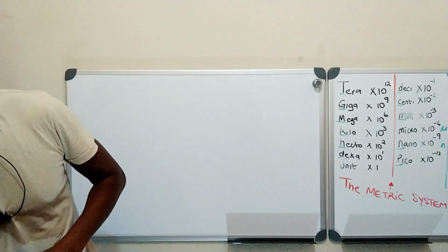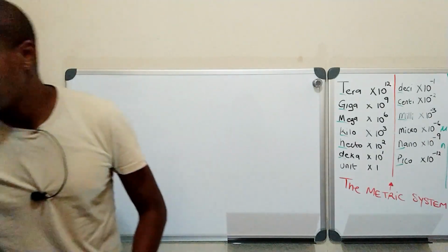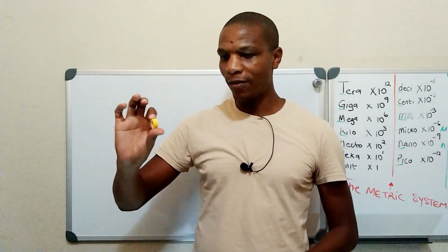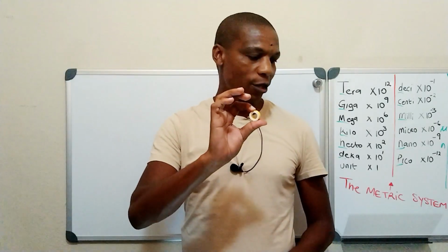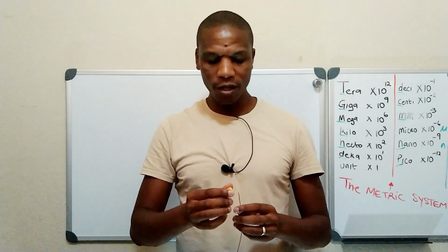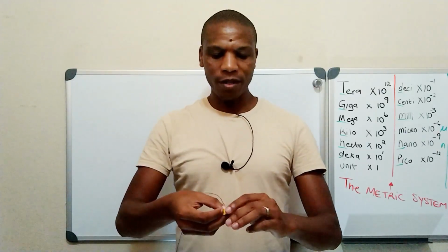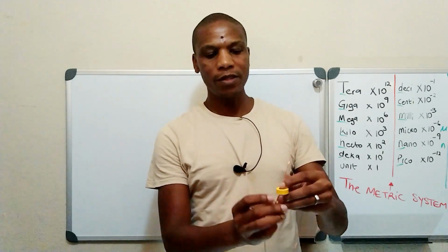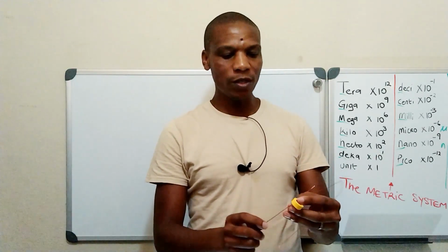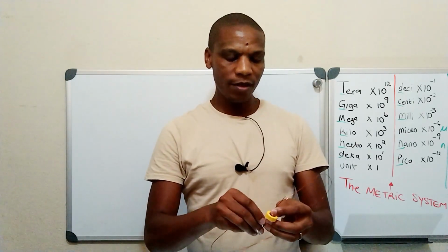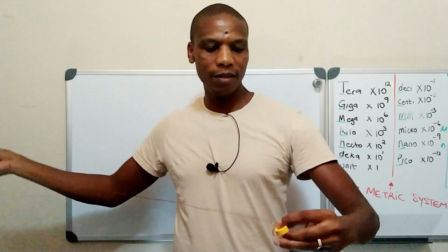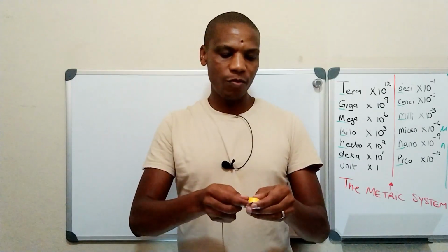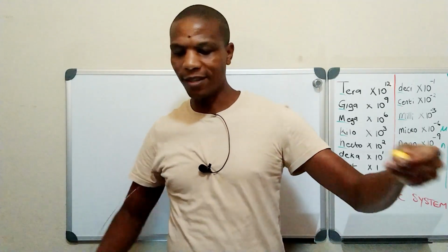Those who are going to make a toroidal inductor, if it's circle like this, they call it a toroidal inductor, ne? Mostly it's used in audio circuits, ne? You're gonna put it in like this. Can you see? And then you insert your wire. Don't let the wires twist, ne? It must be one uniform coil, ne? Make sure that your hand is strong, ne? Then you pull. Easy. Look at that.